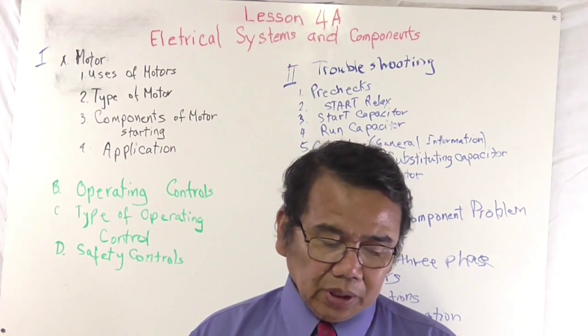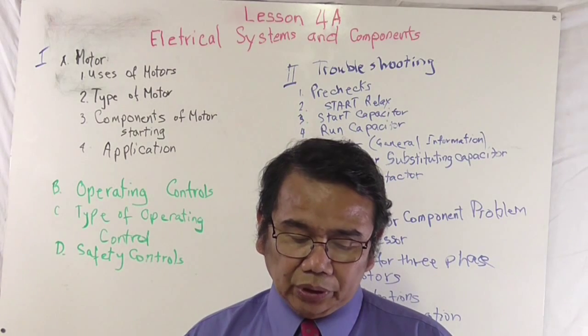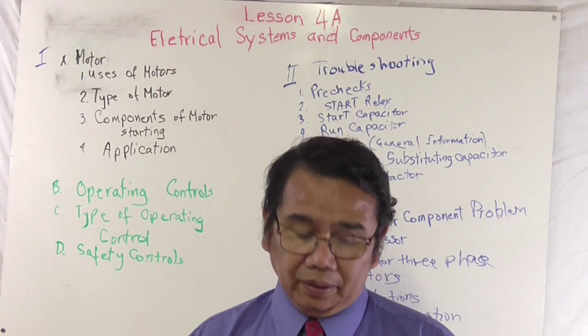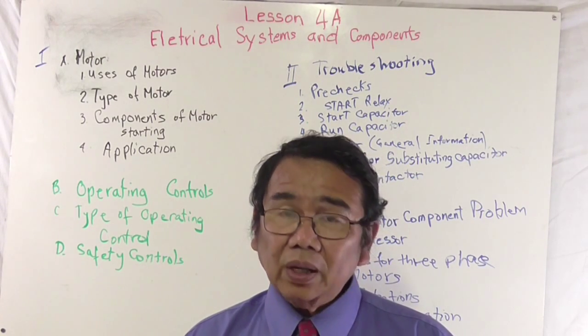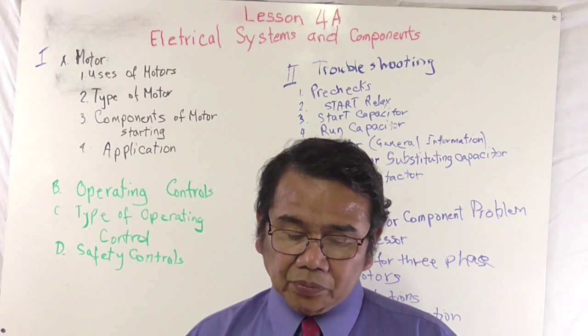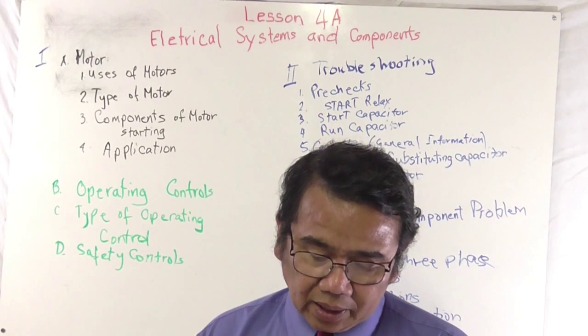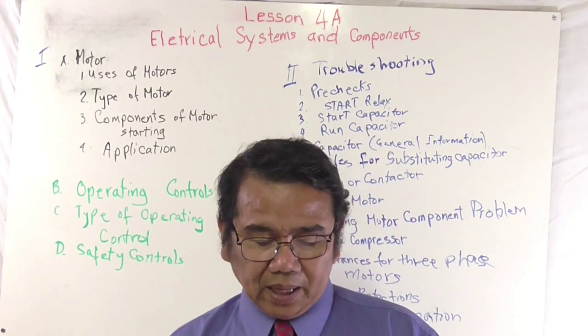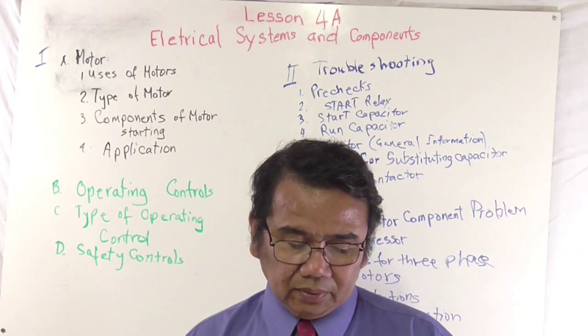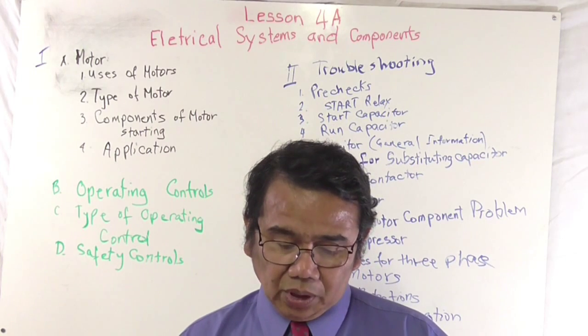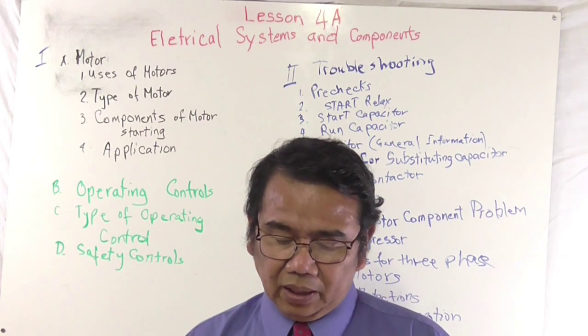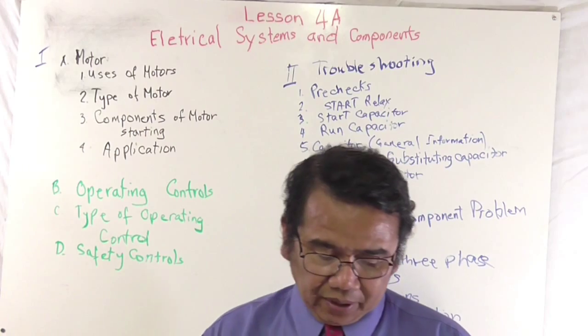And then you've got potential start relay points staying open. Compressor will hum, try to start but not run. In 15 to 20 seconds the overload will trip, cycling the compressor off. This will continue to cycle on and off until repaired.